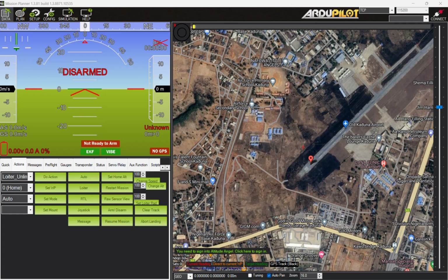When you launch the software, you're welcomed with the data plan screen. You actually have five tabs to play with, but we'll first have a look at the main screen. On the main screen, you have five components, and the first part is the communication connection part of the Mission Planner, which works with the modem that comes with the telemetry module.